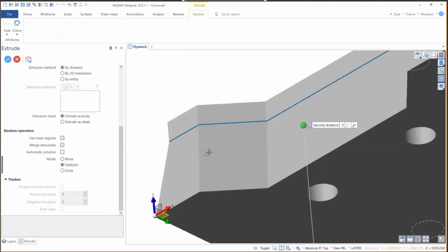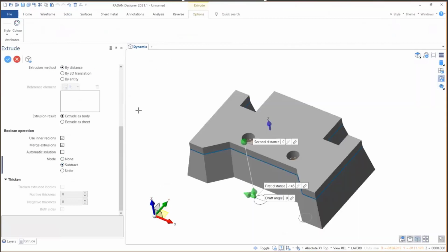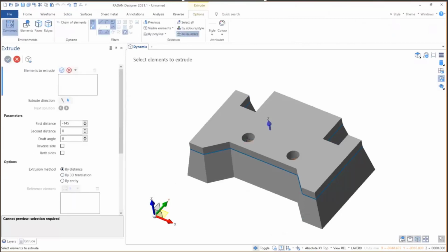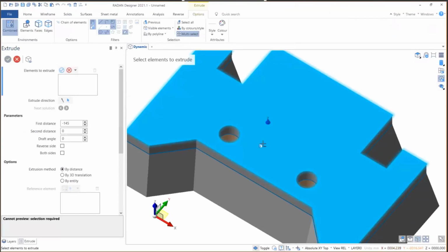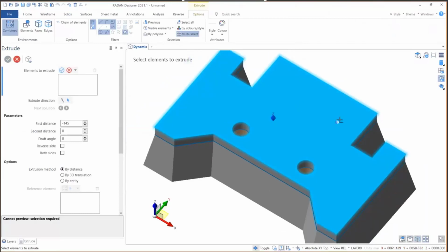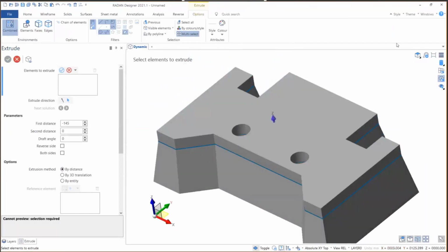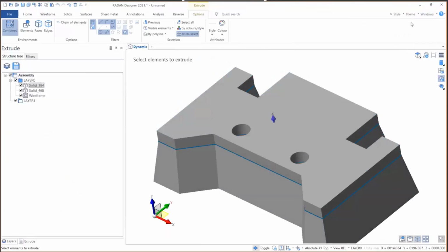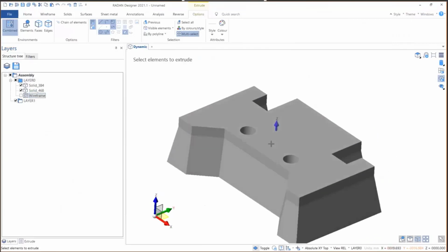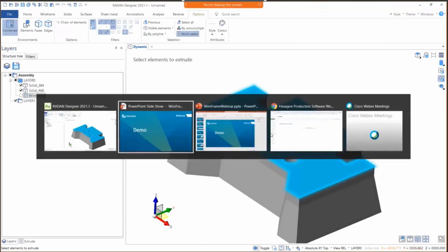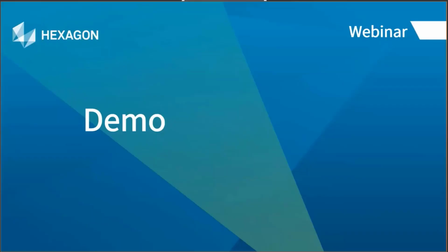So in effect, what I'm doing is adding those holes through the second extrusion, using that wireframe geometry to create multiple extrudes. So wireframe geometry is very, very important. If I go back to my layers, I can turn off the wireframe, and there is my model. So that was a simple example just to get us into using wireframe.